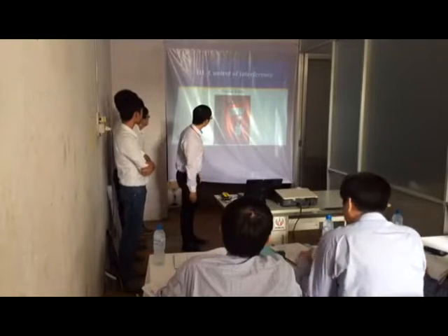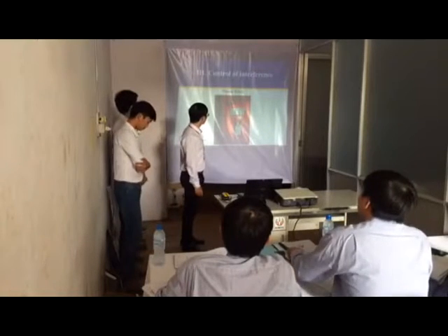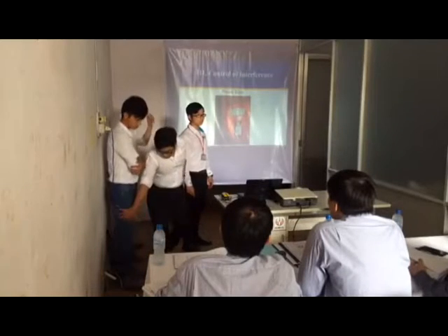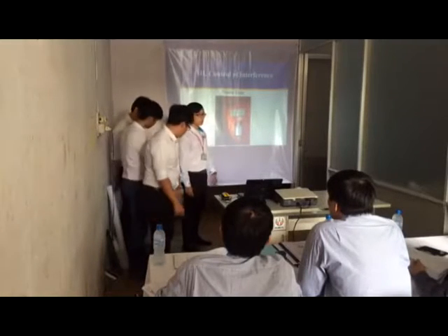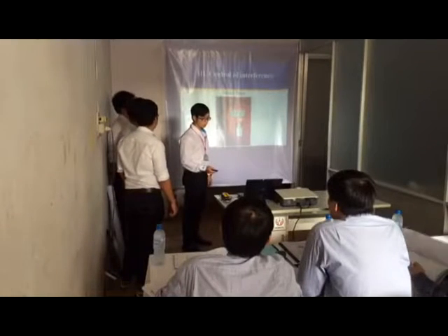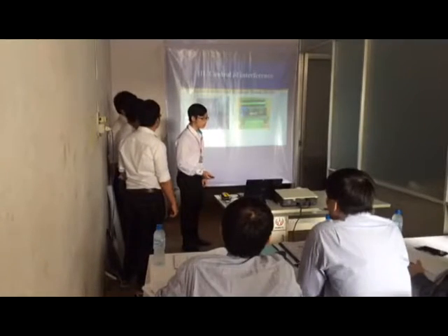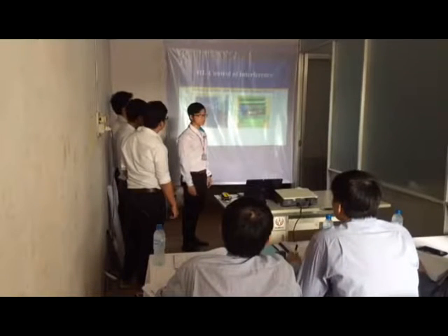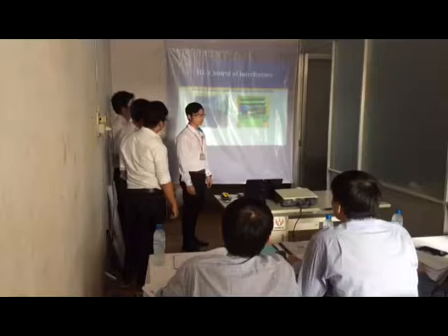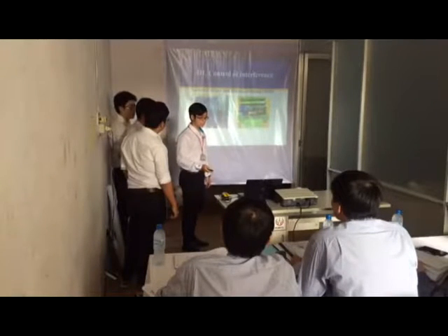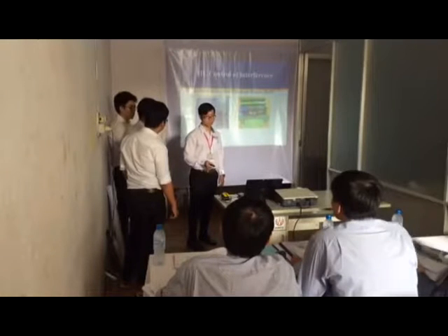Then we use a noise filter to clean the 220 volt alternating current power source before using it. And last but not least, we use an isolated driver and breakout board when transmitting control signals from the CNC control system to every motor. Mr. Quốc will take over from here.